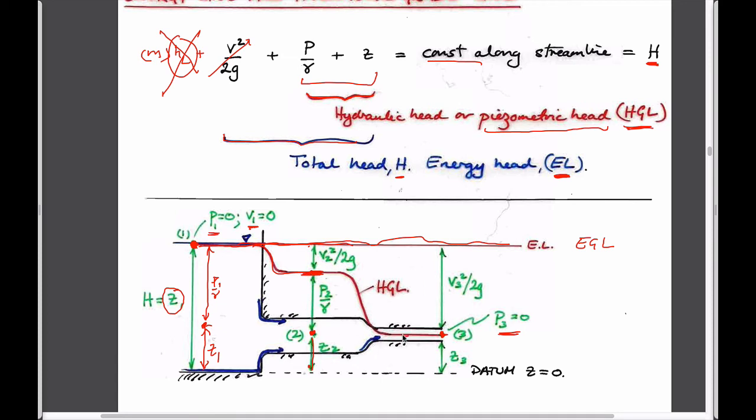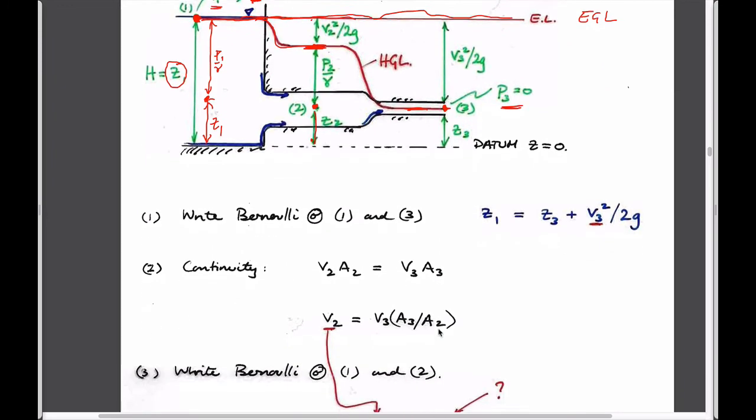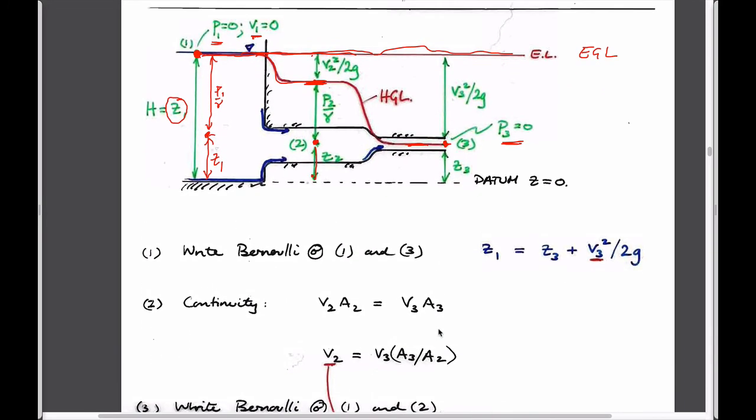And we know the hydraulic grade line has to be at this point here. And so this would just be the velocity coming out of this. The other useful way to think about this is that the velocity here has to be lower than the velocity here, right? Because of continuity. You have the same volumetric flow rate going through this as you have going through this. So V2 has to be less than V3. And that's merely a consequence of this continuity part here.